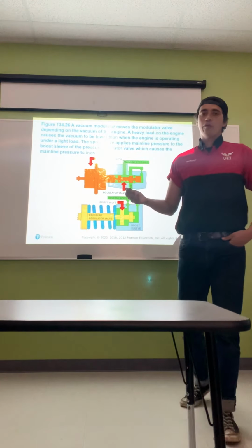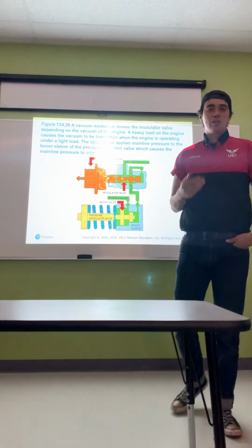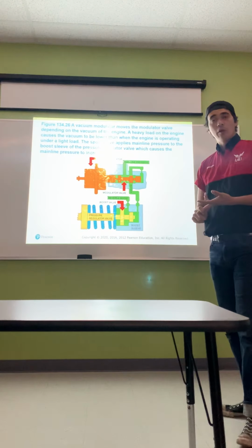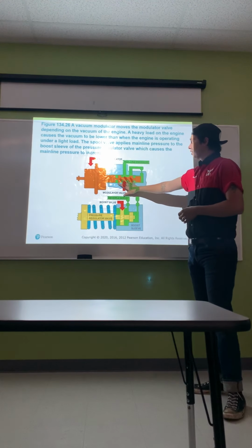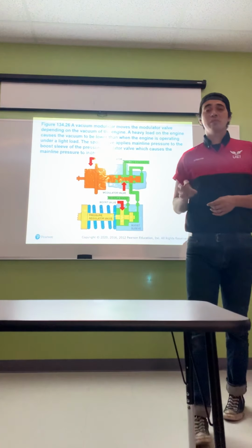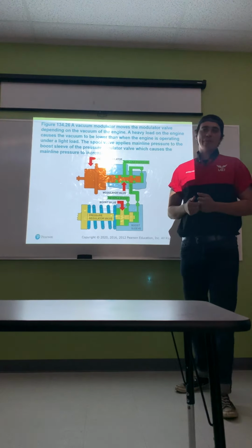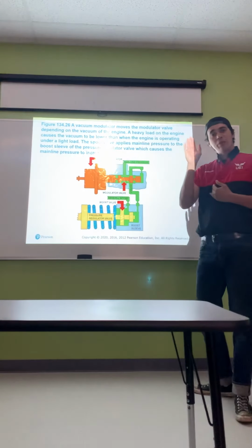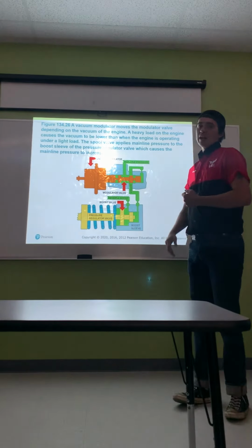You don't want it to go into overdrive when you're trying to go up a hill, especially like, say, the Cajon Pass or through the Grapevine. You're going to be putting a lot of stress and a lot of heat through that transmission. You can burn up the transmission. This vacuum modulator helps keep that transmission from shifting into overdrive. You can manually do it by clicking the overdrive button, turning overdrive off, or on a lot of vehicles, depending on where your foot is on the throttle, it won't allow it to do so by using this vacuum modulator.